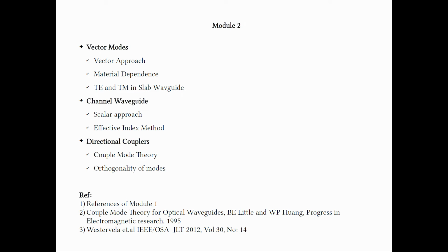One of the most important properties and striking results is that the power launched into one of the waveguides can be exchanged with the other waveguide even though there is a small gap in between the waveguides. The phenomenon is observed to be periodic, and we can periodically couple back and forth between the different waveguides. We can take an appropriate length so that you get the required amount of power coupling from one waveguide to the other.